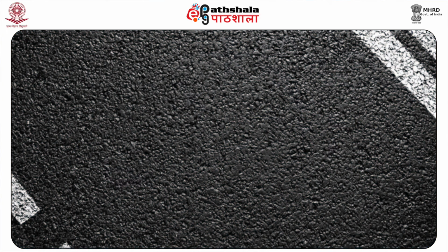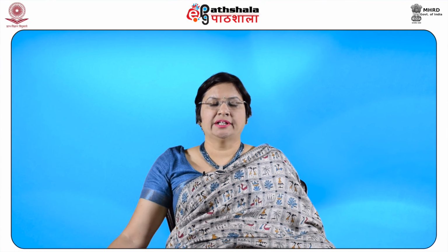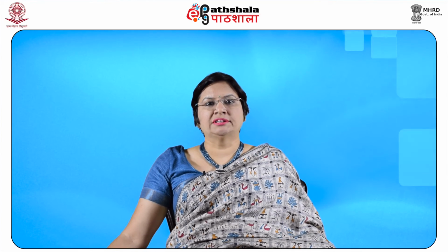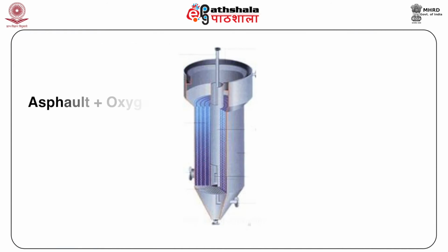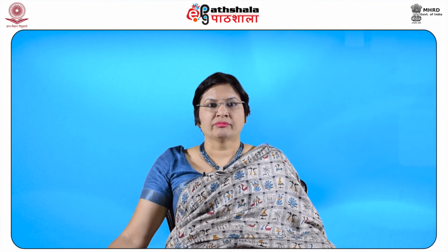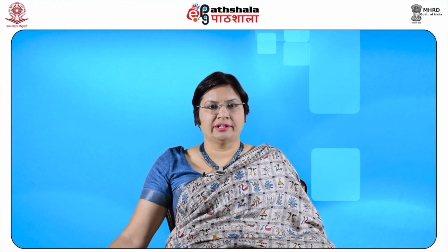So, coming to asphalt, asphalt is commonly used to make roads. It is a colloid of asphaltenes and maltenes that is separated from other components of crude oil by fractional distillation, and once asphalt is collected, it is processed in a de-asphalting unit and then goes through a process called blowing, where it is reacted with oxygen, and with oxygen it gets hardened, and the moment it gets hardened it can be used to make roads. Asphalt is usually stored and transported at around 300 degrees Fahrenheit.